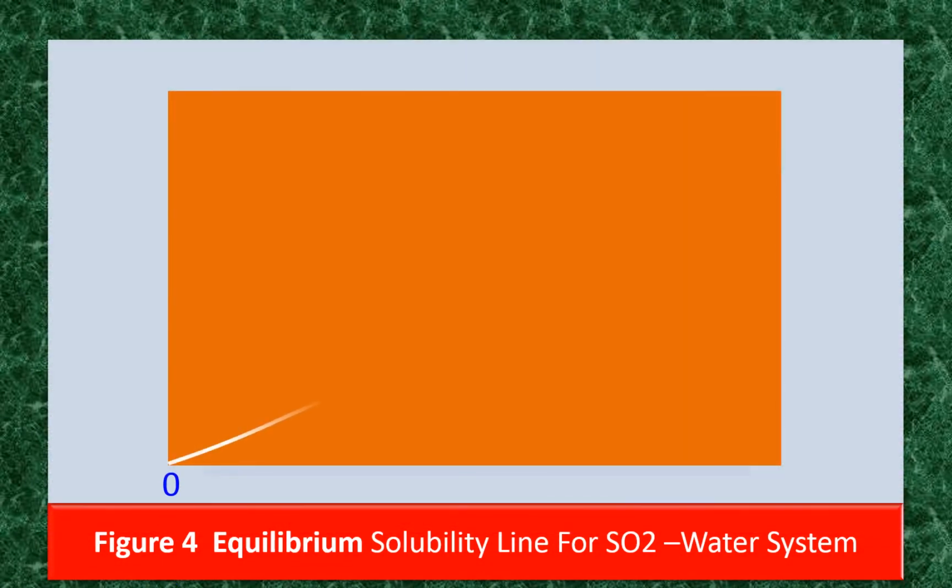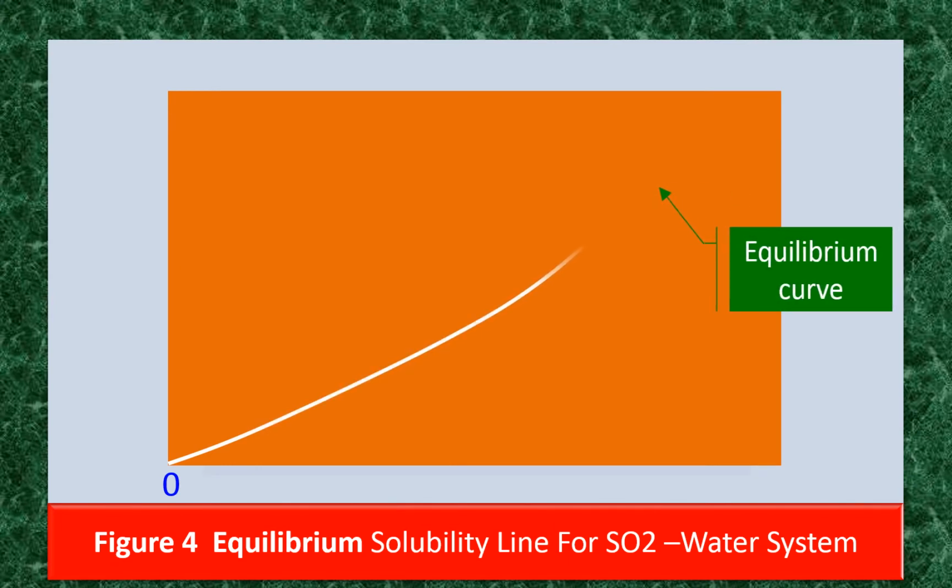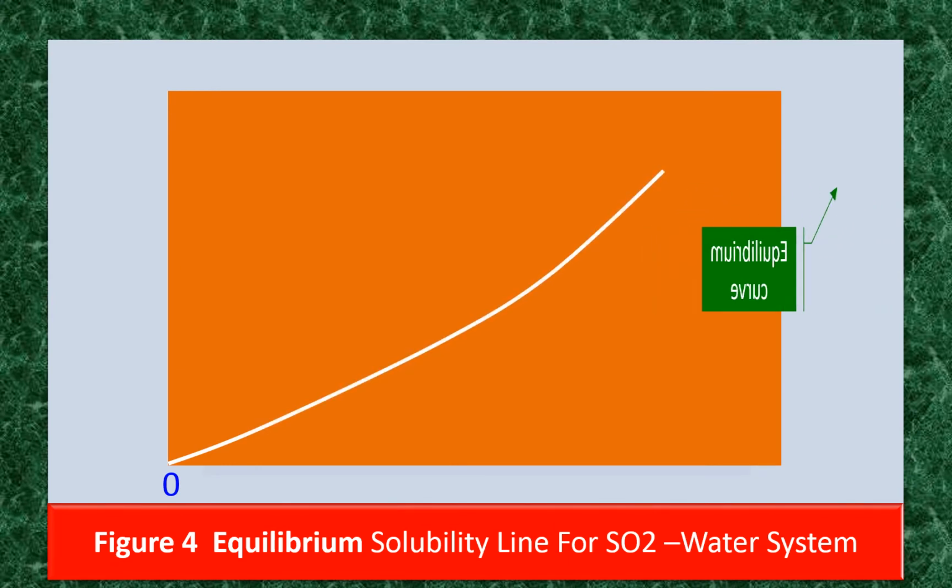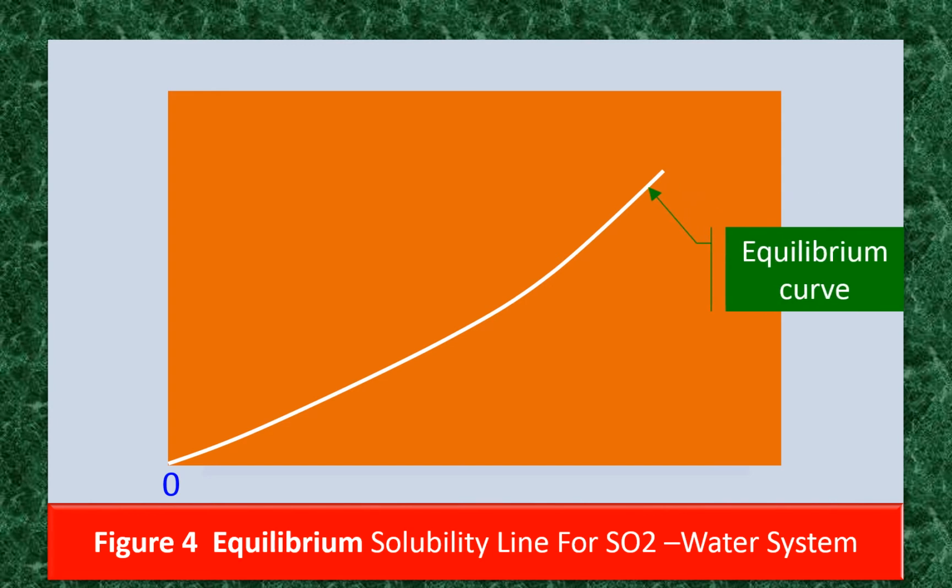This figure illustrates how the liquid flow rate is determined from the equilibrium solubility plot and the specification data provided for the design of the absorption column. From the gas inlet concentration, draw a straight line such that it cuts the equilibrium curve at point O. This point on the equilibrium curve represents the maximum liquid concentration point, the liquid concentration in equilibrium with the inlet gas concentration.